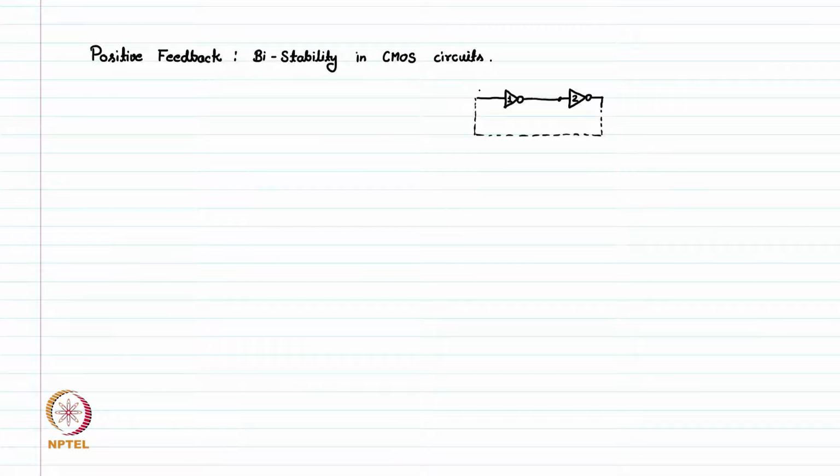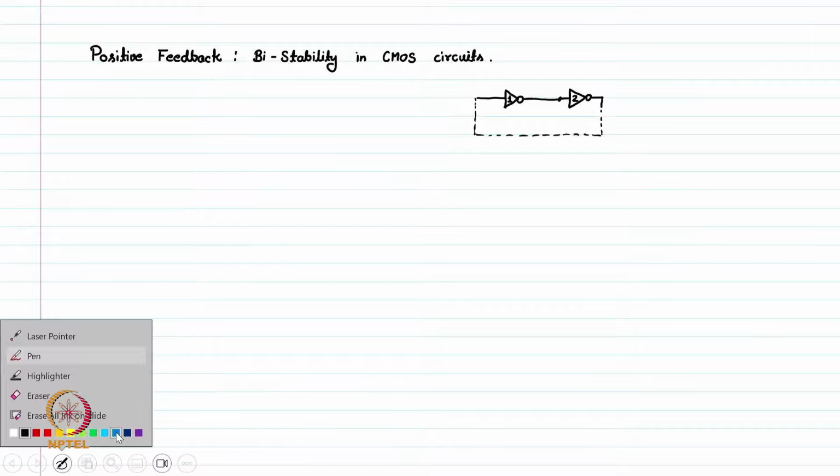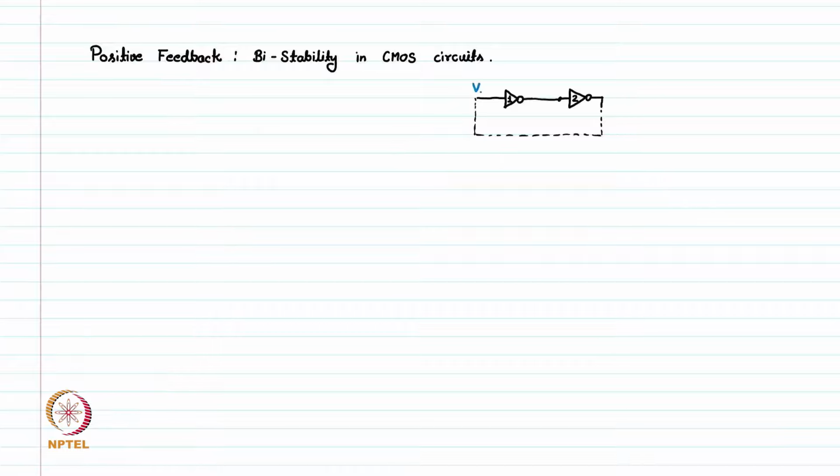So now we have here Vi1 and this V output 1, which is equal to V input of 2, and similarly here this V output 2 is equal to V input of 1. So the output of one is the input of the other transistor. This is how a bistable CMOS circuit looks like, and if we draw the schematic, that looks something like this.